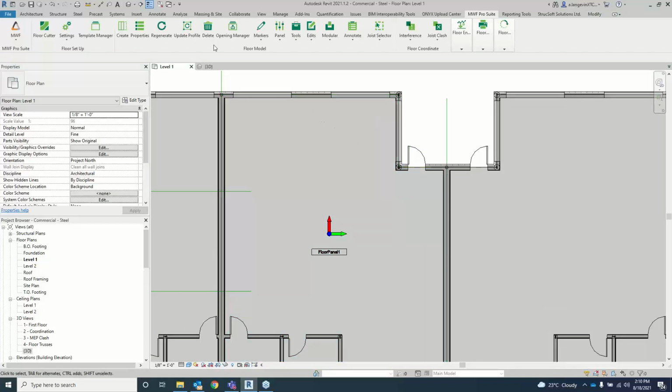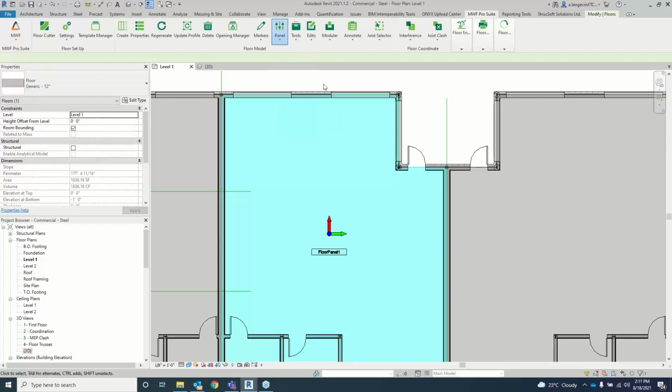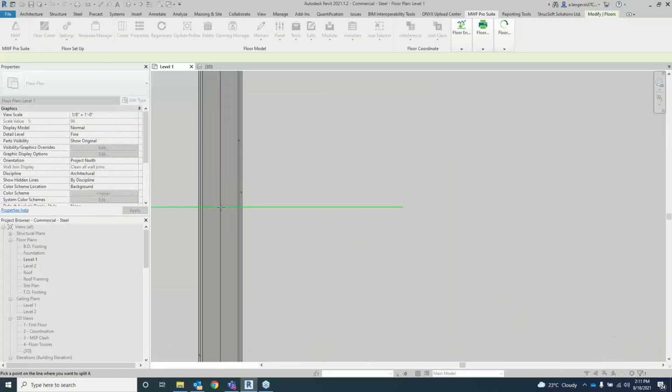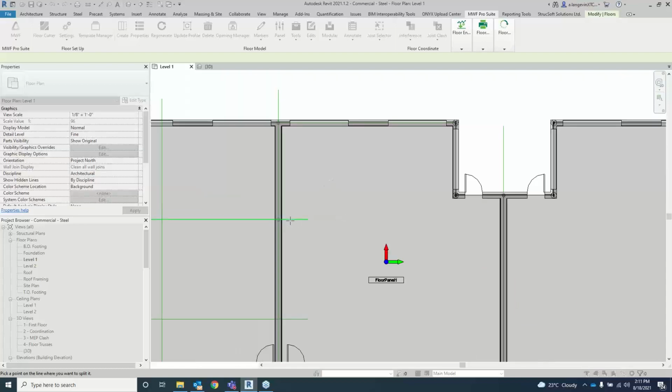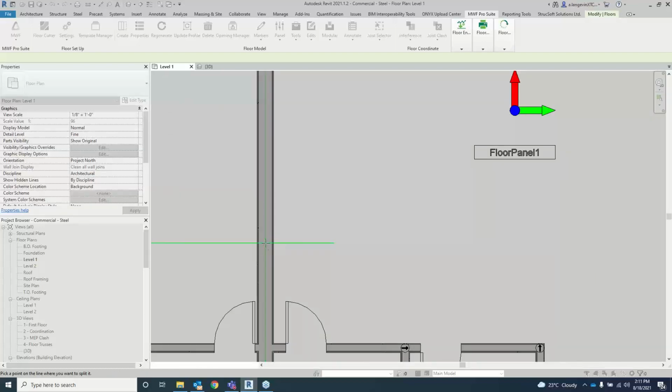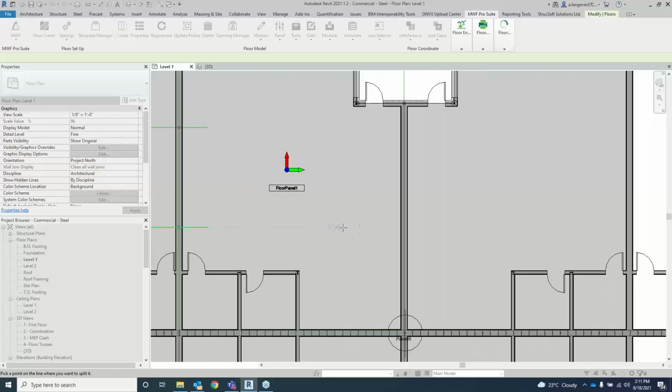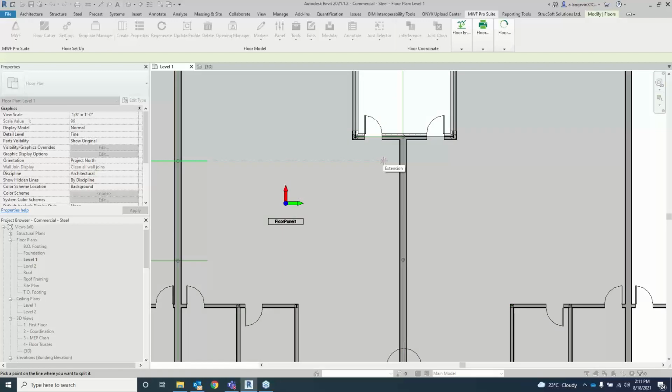And then under place nodes, I'm going to select my floor real quick, do my place nodes. That's going to allow me to drop a couple more of these nodes where I need my splits to be. So I actually have the lines from the other one already created. I'm kind of going to use that as a reference real quick. So somewhere around here, and then we want to do our best to keep this lined up across for when we split. Now, if you don't manage to get it perfectly, that's fine. We're going to go in here and align these regardless.